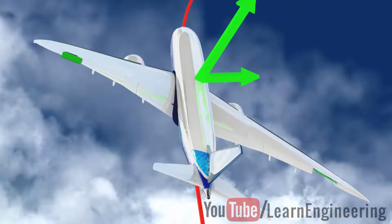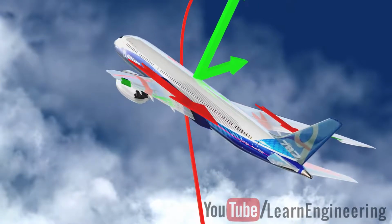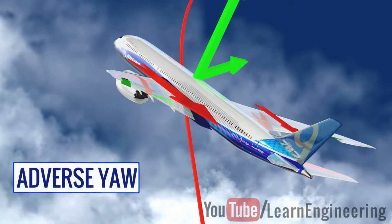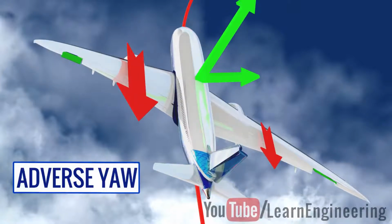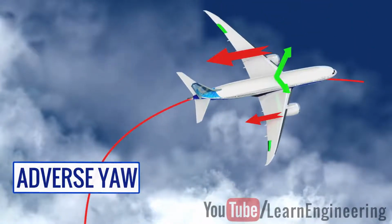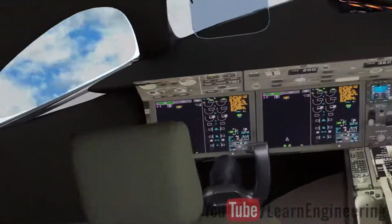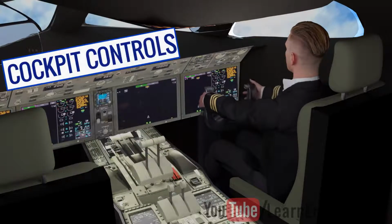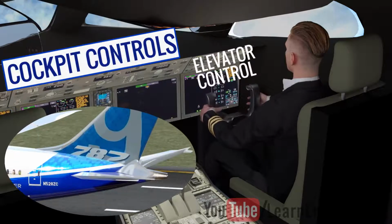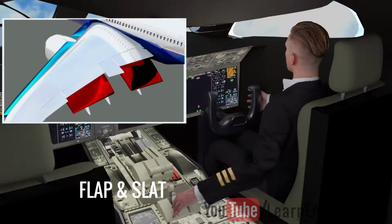When you keep one aileron up and the other aileron down, the drag forces induced on the wings are not the same. This will cause the airplane to yaw. This phenomenon is known as adverse yaw. The rudder has to be operated simultaneously to prevent the adverse yaw. The way pilots control the different wing attachments and the whole airplane is illustrated in this animation. In practice, a control computer accurately manages all these wing attachments using a fly-by-wire system.